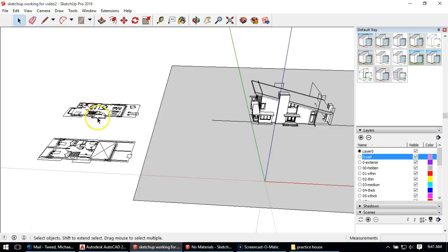And basically what I'm going to do is model my interiors over here, and then make them components, not groups. Then I'm going to copy the first floor over to here, which you want to pay attention to where it goes, and the second floor over to here. That way, if I need to make changes to my interior, I can work on the component over here, and since it's a component, it is also making the changes at the same time inside my building.